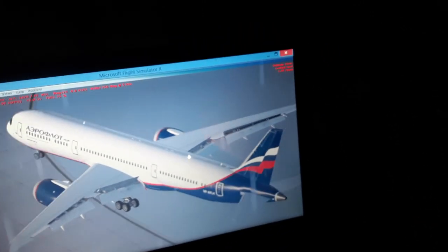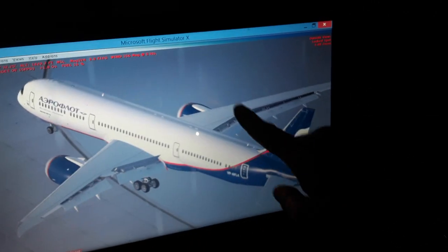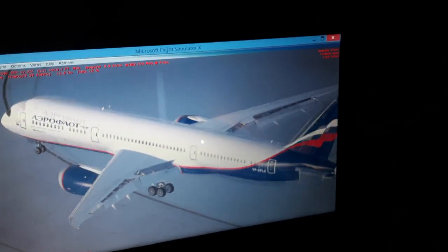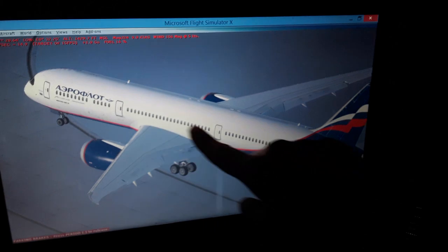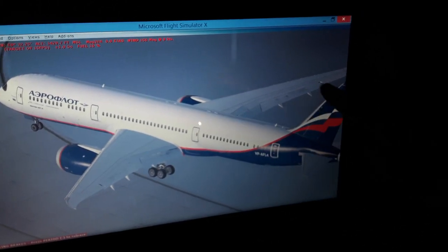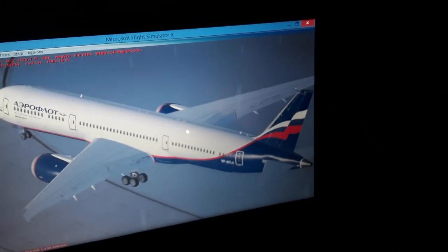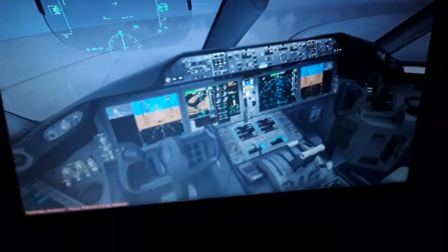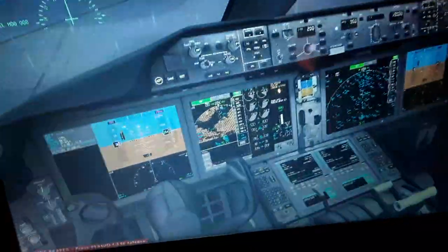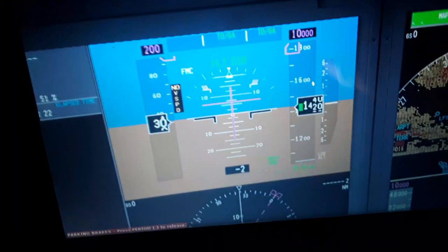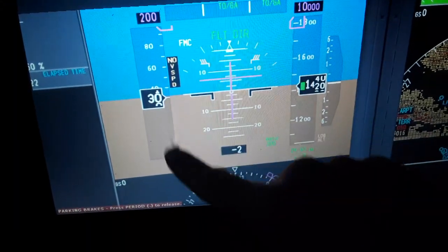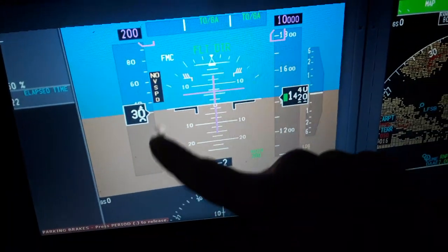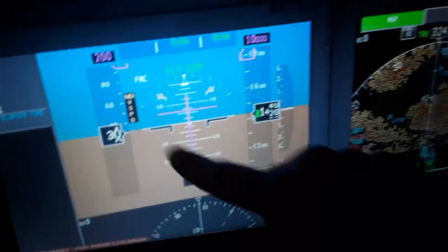So we have also the airflow becomes detached from the top surface of the wings as we fly for a given angle of attack and airspeed. This is the stall speed, where the airflow becomes detached and the aircraft wings stall in the air. So we need to pay attention when we fly. Over here in the airspeed tape, you will see the airspeed indicator. The airspeed indicator over here, you can see the stall speed display with a number yellow and red indication.